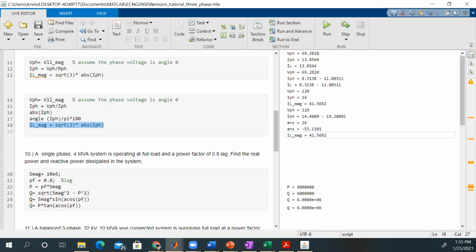electric and magnetic fields of the system. So within the system at different places, you'll have coils, or even on your wires that are not coiled, there is some inductance. The current generates a magnetic field, right? You get an electric field as well from the voltages. And if you have capacitors or inductors in the system, it concentrates these fields. So the energy in these fields is what we call the reactive power.